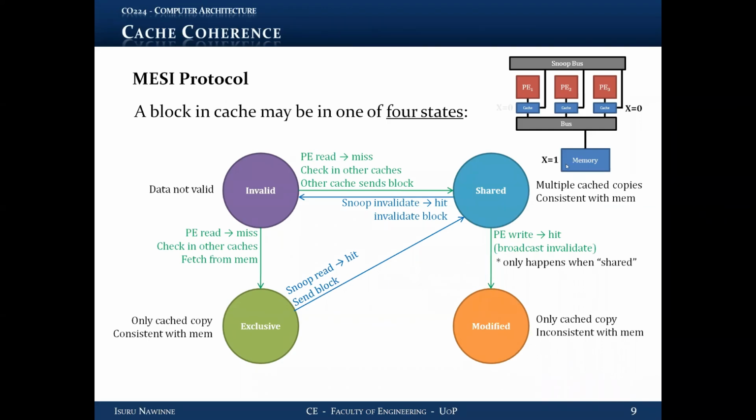So when this latest step happens, processor 3, which had cache 3, which had the modified copy, writes back to the memory. So memory goes from x equals 1 to x equals 3, now has the up-to-date value consistent with everything, and cache 3 sends the up-to-date data to cache 1, right?